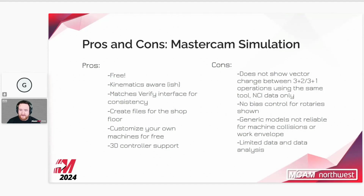Now, the downside of Mastercam simulation, it is still reading just the NCI data. This means that it's still not going to show us any kind of vector change between operations using the same tool. We don't get to see that tool move around. We also don't actually have any control for the rotaries in terms of the bias.